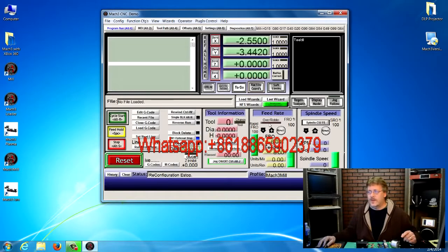This box right here is our feed rate, and we can make the machine go faster or slower by manually moving the plus and minus sign. And you might want to slow the machine down a bit if you're cutting into things that are more critical. Over here is the spindle speed. If you have a programmable spindle, you can adjust how many revolutions per minute it spins.